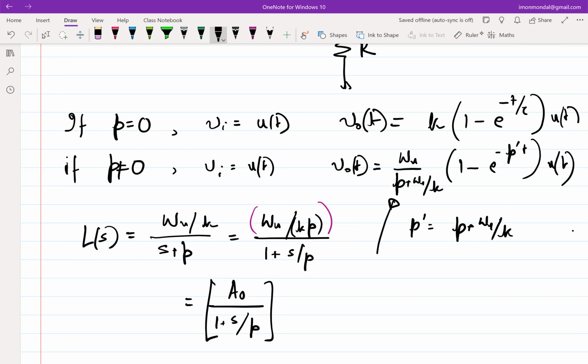As a designer, when you are designing for a specification, if somebody tells you, hey, I want an amplifier for signals that have 100 megahertz bandwidth, and you have to amplify them by, let's say, a factor of 2, then you have to use negative feedback, and the UGB of the negative feedback loop should be at least 100 megahertz. Obviously, you don't want a case where UGB is exactly 100 megahertz, because this is again a Bode approximation, and you don't want to cut it very close. So you would want to leave some margin, but at least you know where to start.